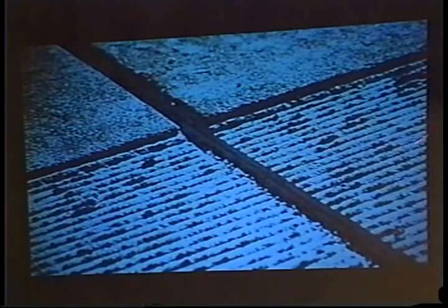Here's what it looks like, the diamond ground surface versus the existing. Probably anywhere from 1/8 of an inch to maybe 1/4 of an inch high end, typically taken off. Gives you a corduroy appearance, longitudinal grooves at that point, good friction characteristics, good pattern for allowing drainage away from the tires to help eliminate any hydroplaning problems.